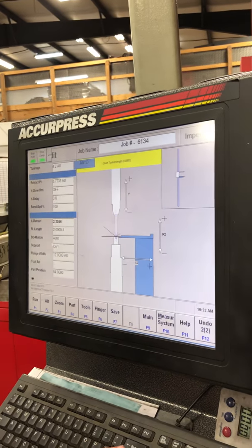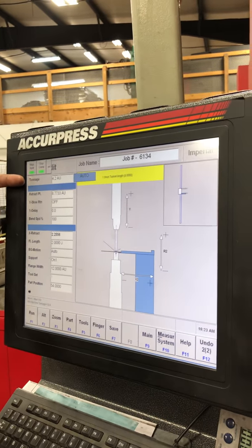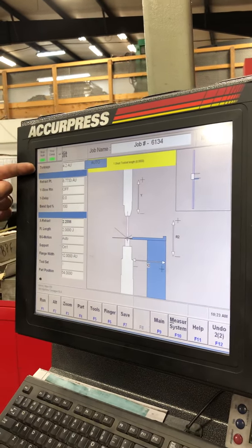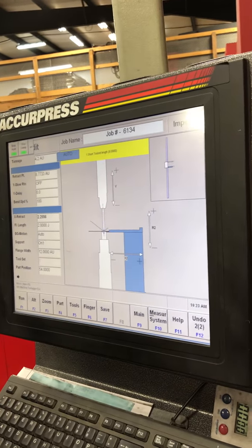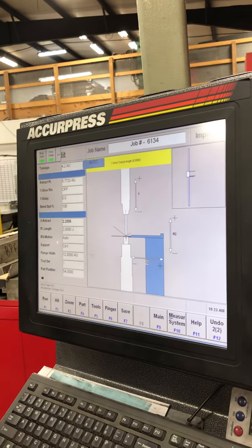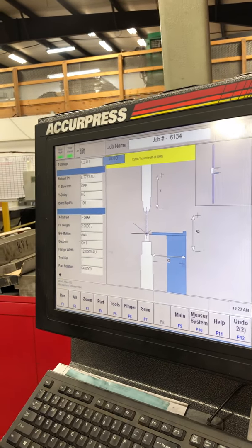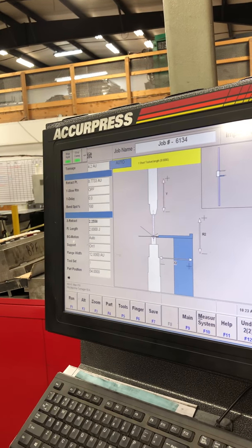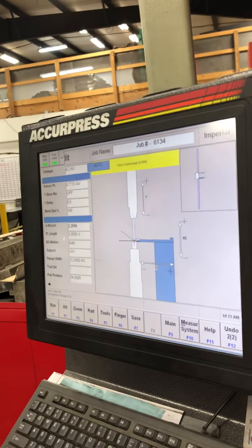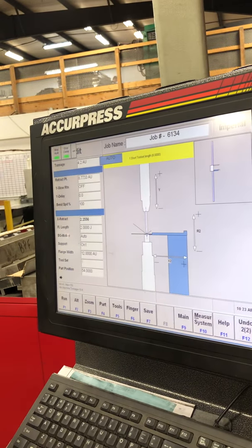Right. And then we'll have our second page, tells us what kind of tonnage we want to run. You know, if the 4.2 tons isn't enough, we'll give it more tonnage. Right. And is tonnage related to anything like speed or? Not really. The higher the tonnage, it might take a bit more for the machine to push it, but these things are very accurate that they're going to push that tonnage to get to that target. So if we push it at 5 tons or 50 tons, what's the difference? Say, depending on what you're forming.